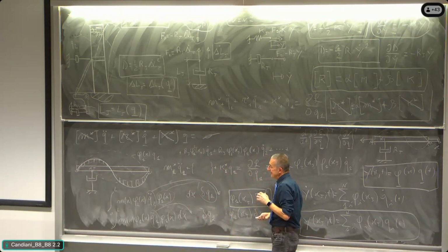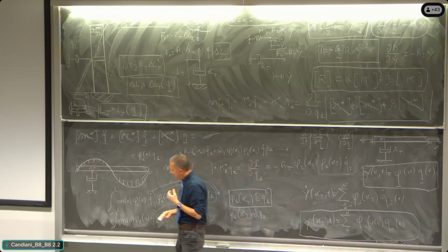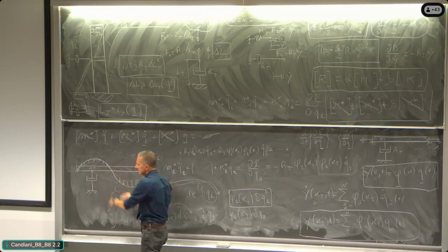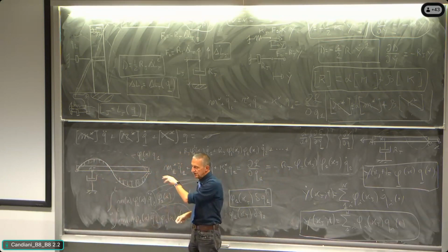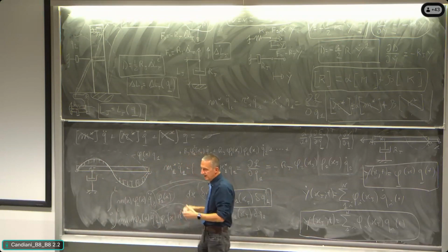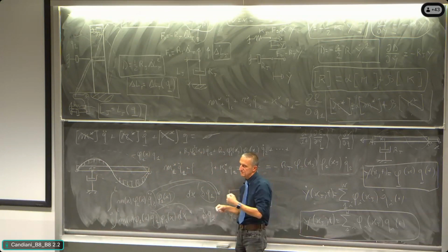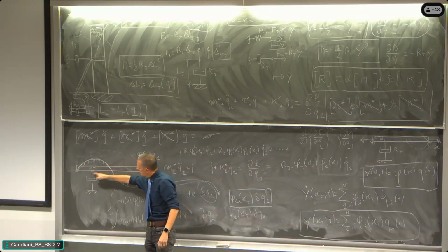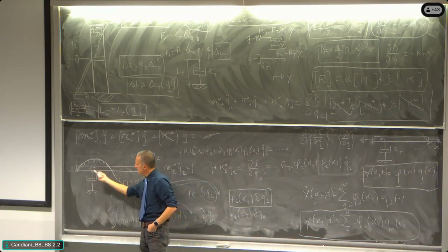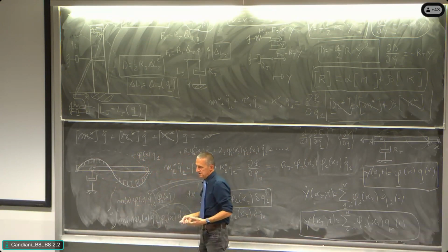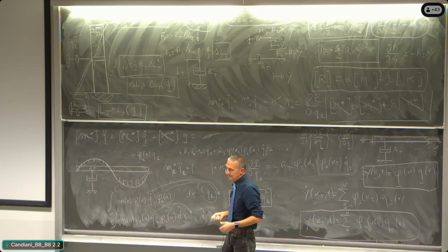I would like you to have the vision that the concentrated damper is coupling the modes, going into the details of the way in which we write the work associated to a virtual displacement, taking the derivative of this work with respect to the variation of the coordinate, and making it work with the actual force that is associated to another mode that is running, and looking at what is happening, that we are coupling the two things.